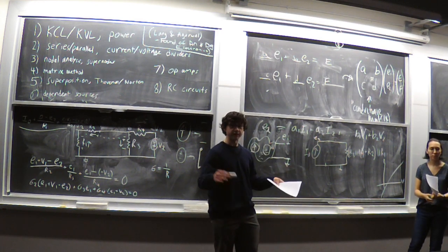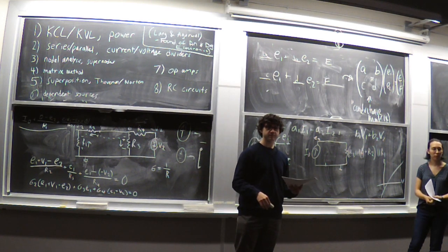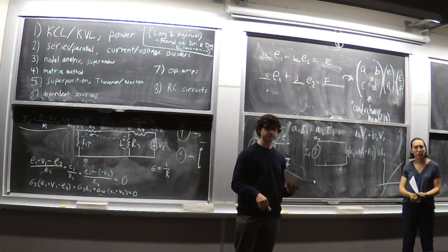Right, and capacitors have to do with the derivative of the... I'm just thinking because at time equals 0, you can treat the capacitor as a short.